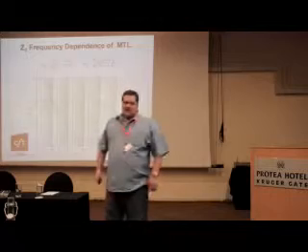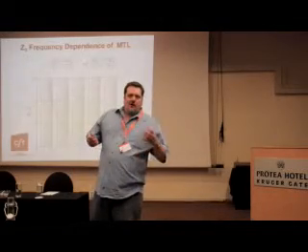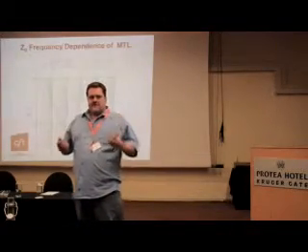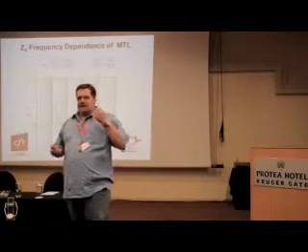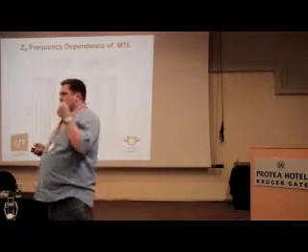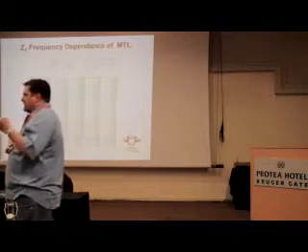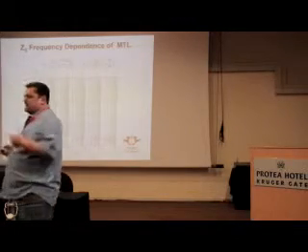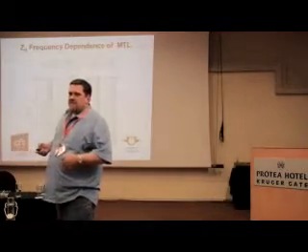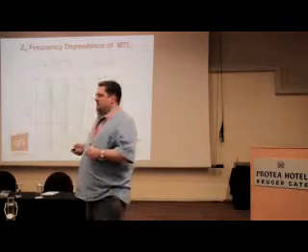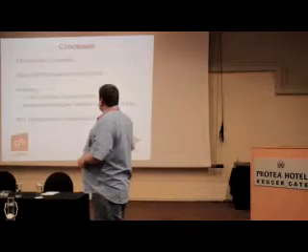The reason is, transmission lines are lossy systems, and their inductance, capacitance, resistance, and conductance are actually frequency dependent. And that makes it very difficult to predict exactly what the common mode is going to look like.